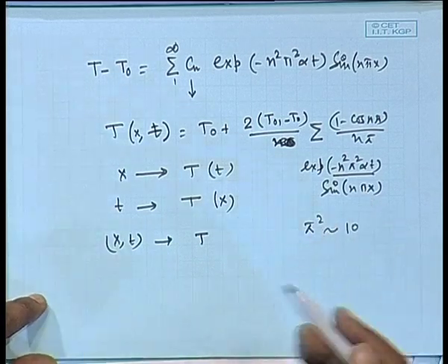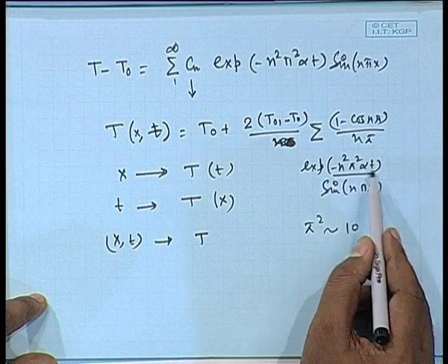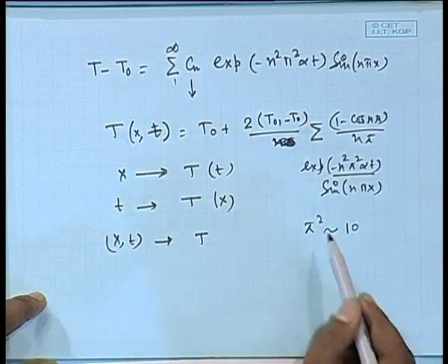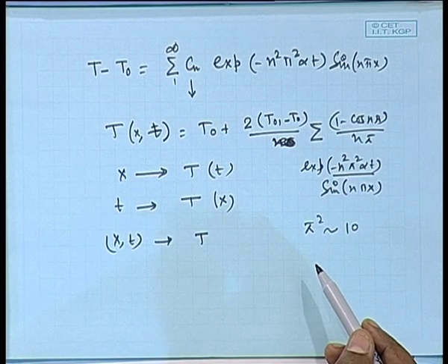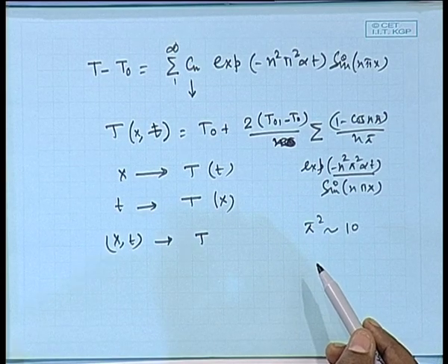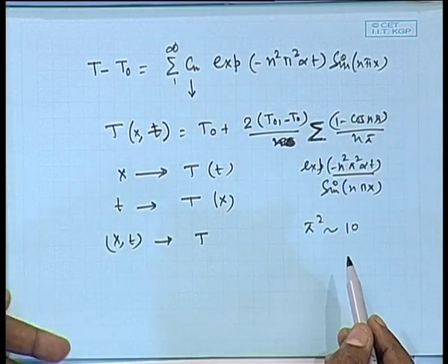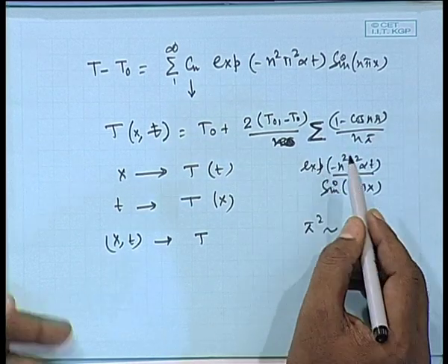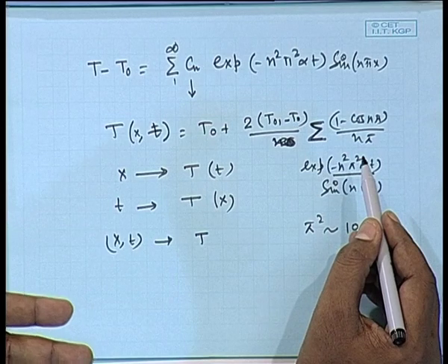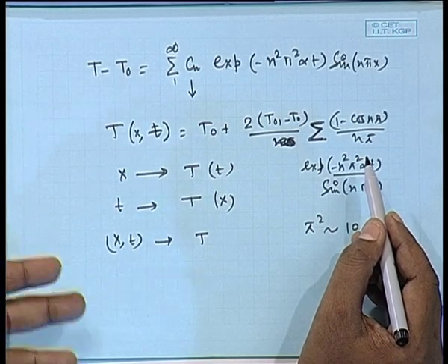Okay. So, as you go up to the higher eigenvalues, this exponential minus term will be very dominant and the whole term will become very small. The contribution of higher eigenvalues towards the solution of the problem will be very small. So, you need not compute beyond 4 or 5 eigenvalues. You need not compute this summation for an infinite number of n's. You can go up to the third or fourth eigenvalue and see the change.